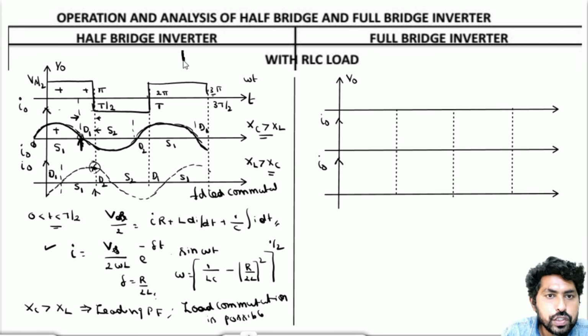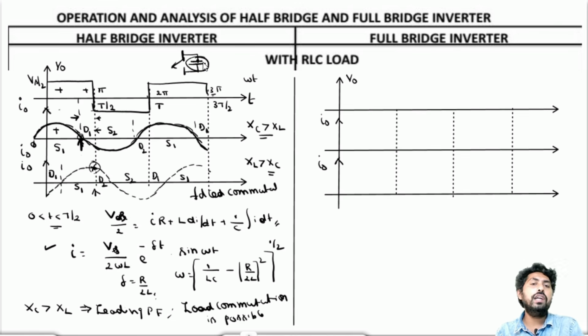At this instant, pi minus pi, the diode gets into the conduction state, so the reverse voltage is applied across the device. When the diode is on, the reverse voltage applies across the device, and this period is called the circuit turn off time.